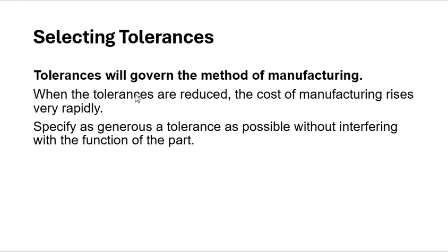When you think about the cost factor, if you play with the tolerance and you reduce the tolerance, your cost for manufacturing is going to go up. There's a serious relationship between the tolerance, how engineers and the drafter make it, and the cost of your manufacturing. They're pretty much related, and you have to be very careful when you deal with that. You don't want to make the engineer angry, because people with knowledge, if they really want to be bad, they can be so bad, and the effect is also so.